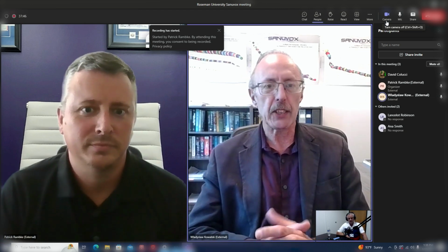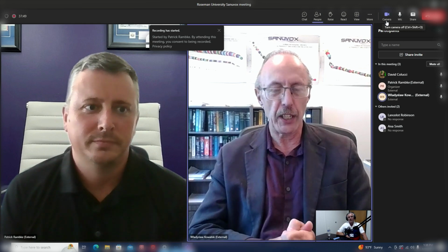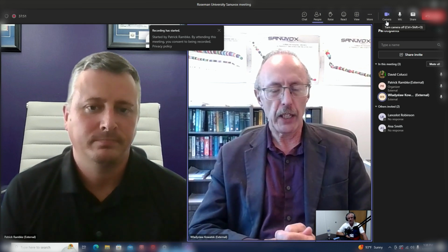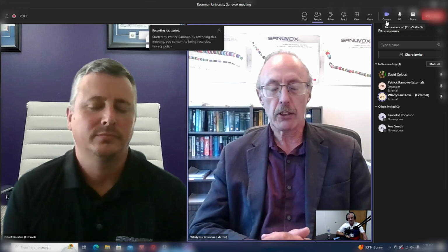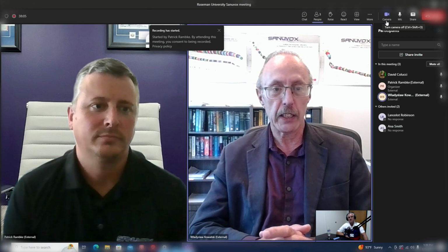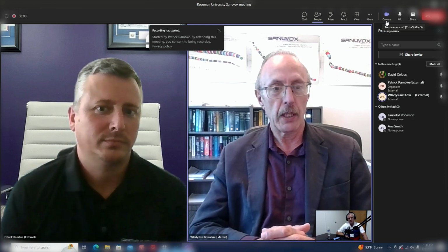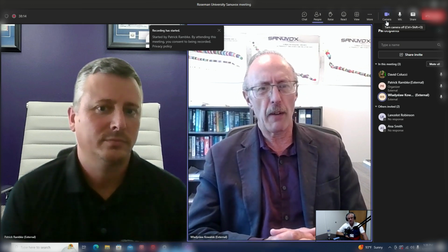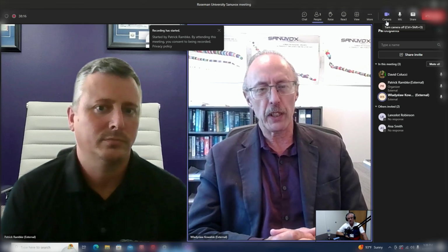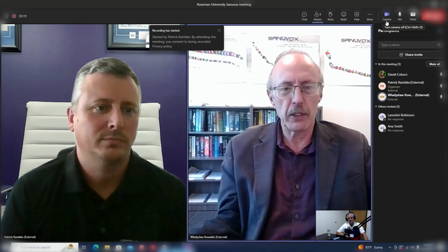If you have a medium pressure lamp or a far UV lamp emitting wavelengths that generate ozone, then ozone gets generated. The ozone often reacts with water molecules and oxygen in the air to form hydroxyl radicals. Hydroxyl radicals are very good scavengers of other chemicals. They will destroy just about anything in the air, and they are relatively short-lived. So hydroxyl radicals are not so bad because they're short-lived. We often can't even record them in the air, but we know they're being produced because ozone is being consumed, especially in highly humid air.